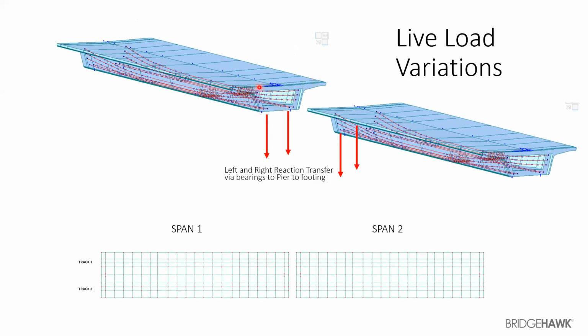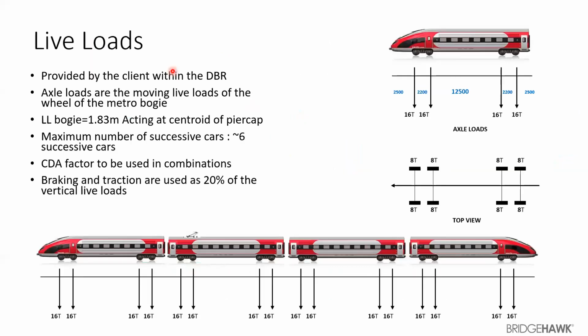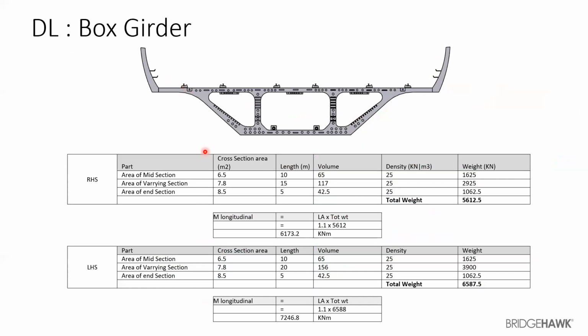It will have an additional diaphragm to counter the shear forces. So the dead load from this one segment would be different from the load which is going to come from the other segments. So when we're trying to have a manual calculation, we'll bifurcate the box girder into three different parts. We'll have the diaphragm section or the end section, the loads from the varying section, and then the third section, which is the midsection. All three types of section will have a cross-sectional difference.